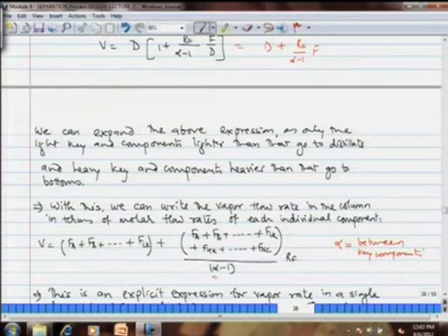So, when you apply this particular expression for each column, you have to see carefully where the column is splitting the feed. So, if the column is separating A, let us say you have a 5 component mixture and the first column separates A from B, C, D, E. So, the split is between A and B, because components heavier than B are all going to end up in the bottom. So, for this you have to use alpha AB, but in the next column let us say BC is being split from DE, as in one of the sequences we saw. Okay. After separation of A from BCDE, we are left with quaternary mixture BCDE, and let us say that quaternary mixture is being split as BC and DE, then you have to use alpha CD, because there the split is between the key elements C and D.